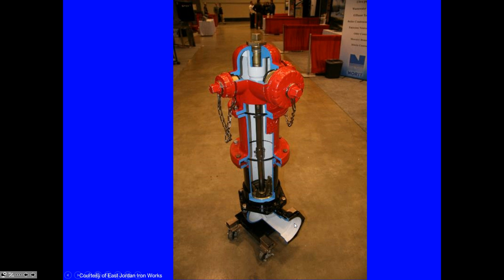You may occasionally see some fire departments will do it themselves, others will have the water company do it. But we were talking about iron and manganese and how they have the potential of coming out of solution because they precipitate and they can clog pipes. Especially if the fire hydrant is at the end of a water line, and there isn't water being used very often, then even if it happens slowly, there can be enough precipitation of iron and manganese that it clogs the pipe.